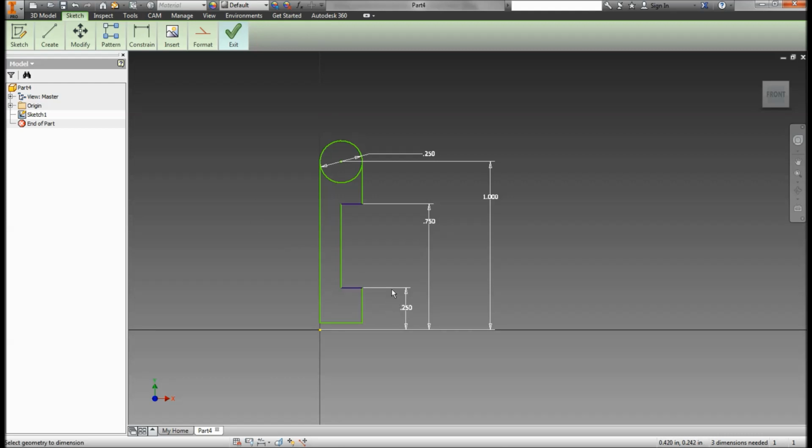Okay, and if I look at the drawing, then I know that's right dead center of the hub is where that reference line is. So I'm thinking that this is probably half of 0.250, which is 0.125. So the distance from here to here should be 1.125.